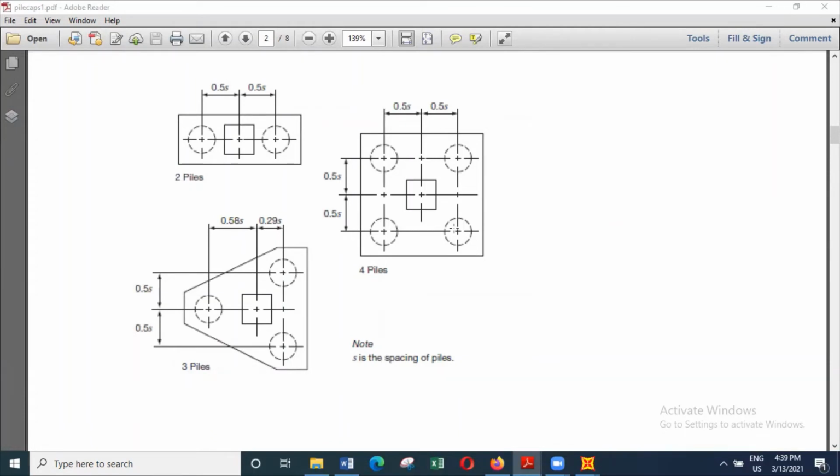When you consider that enhancement, you will find it's hard for a pile cap supported by 4 piles located 3 times diameters or less apart to fail in shear.